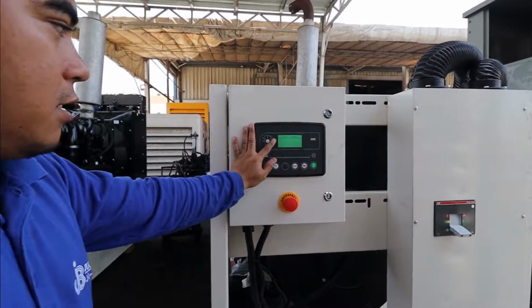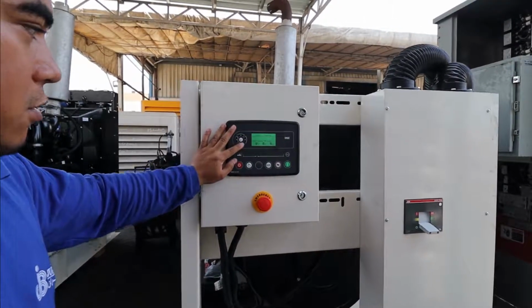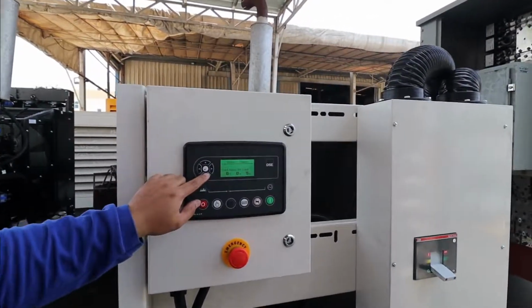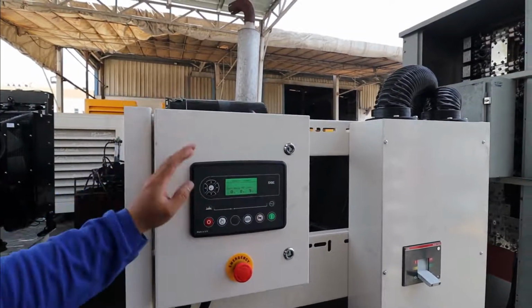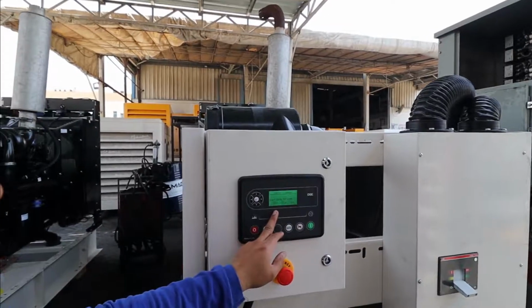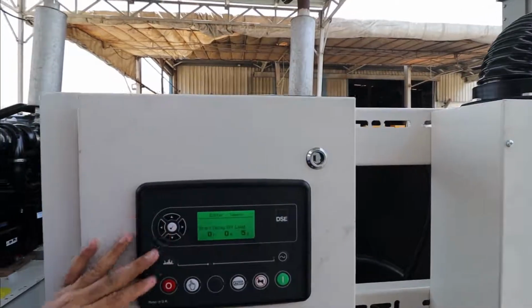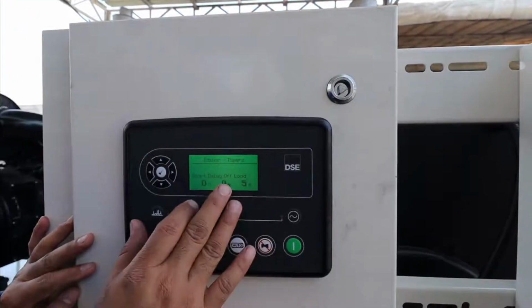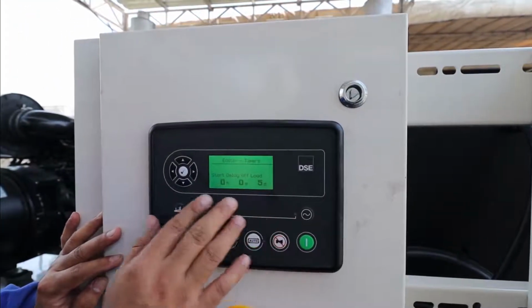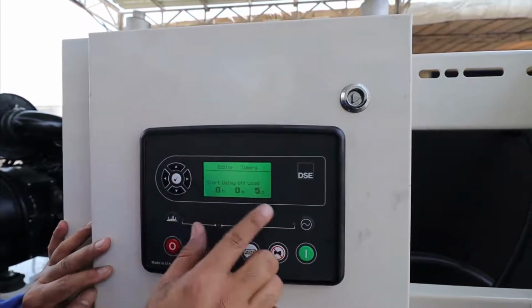So just scroll here, going to your timer. Now you can scroll down. From here, you can see the delay 5. If you want to change that one, you just check this one. You can see it is blinking. So now you can scroll down or up if you want to change the parameters here. Once you have changed it, just long press this one and it stops blinking.